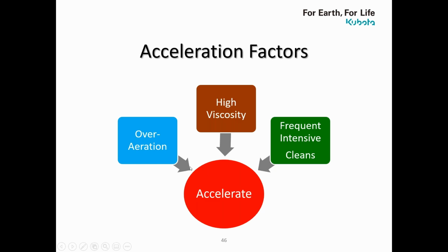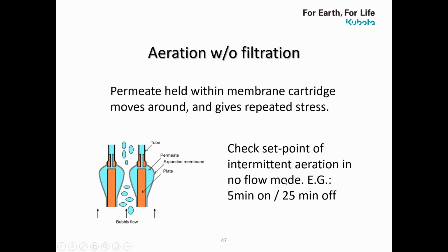And keeping the membrane to a longer lifetime, and please do not over aerate, or you have a lot of relax time. If you relax a lot, that could be a little bit stronger to the membrane. Higher mixed liquor, high viscosity can be a little bit more difficult. And also, if you do chemical cleaning like every week, or every 3 days or something like that, it's going to be intensive. It's not going to help the lifetime. So we want to help you to maximize your lifetime and make it easier operation for the membrane.